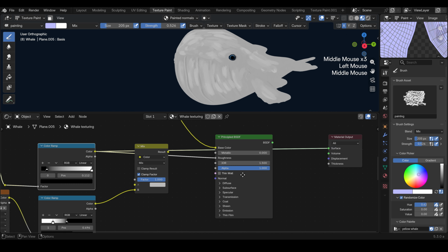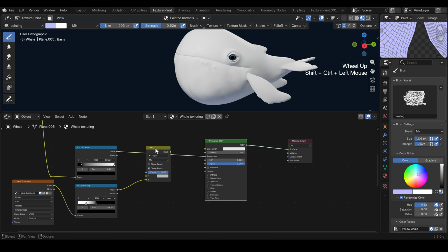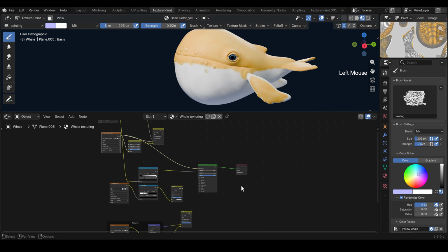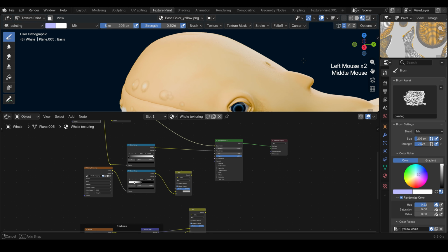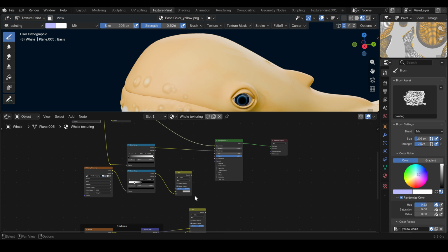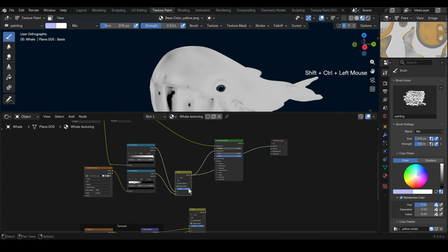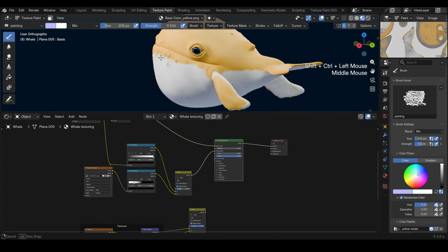Let's see how this impacts the roughness without any other variations. So I detached the color as well. So I have just the Principled BSDF, and of course let's connect the simple color. These kinds of subtle variations are pretty fine for the roughness. So let's connect this back and reconnect this to the general roughness input. And of course, to mix them nicely, we need to bring down the factor just a bit. So, okay, this way we have the mix of the two roughness maps.